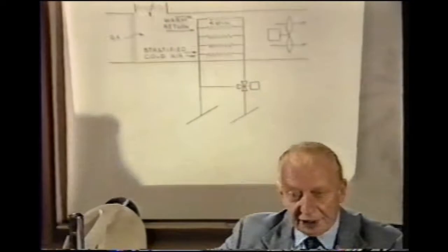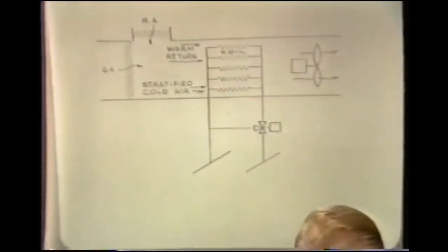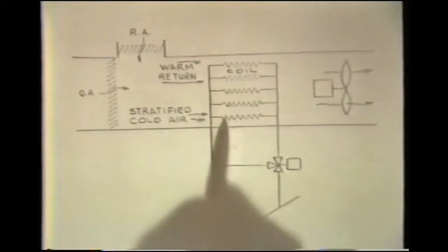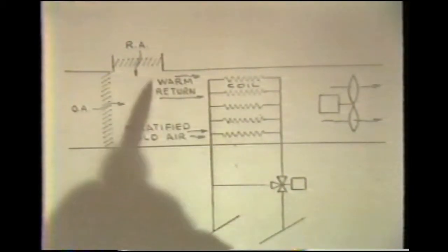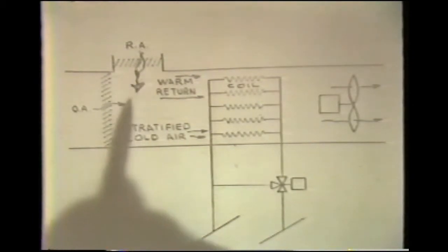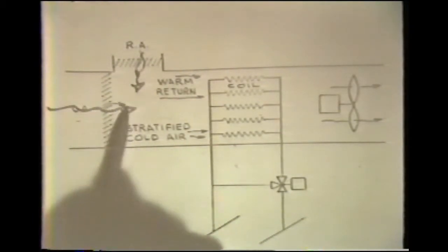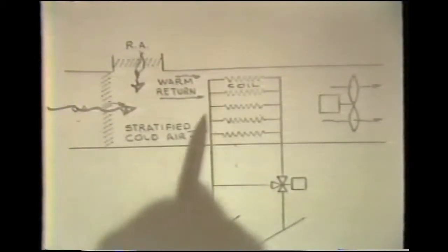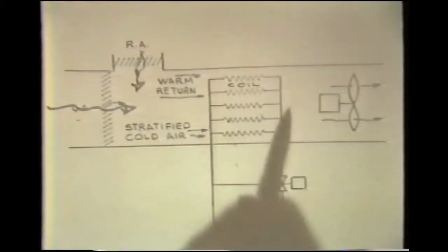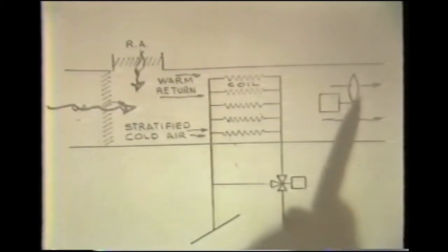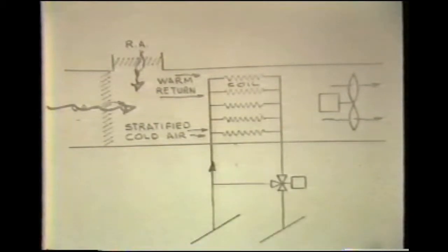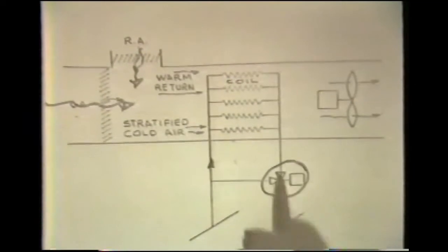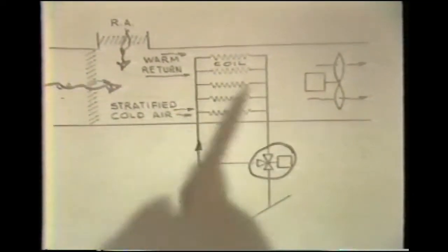In a basic heating cooling system applied commercially, we'll quite often have a coil in the air duct supplying the building, which will take return air and outside air, causing this to flow across the coil to provide either heating or cooling to the building, dependent on the water temperatures being supplied. And the load characteristic for this is quite often stated by a three-way control valve.